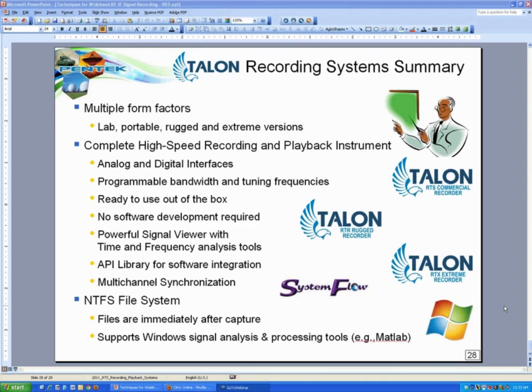I would say sometime in third quarter, probably, is when it's most likely going to happen. The technology is evolving through what we call our Onyx, which is a Virtex 7, and that board will be available during July, I believe it's scheduled for. Right after the board's available, we'll be putting it into a recording system and then pushing the data rate up as high as we possibly can. The goal is to go to the full rate at 3.6 gigasamples, 12 bits.